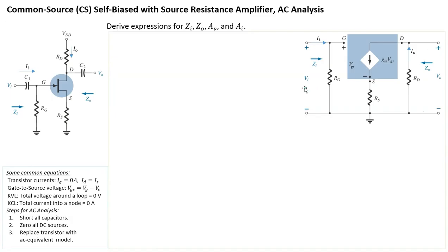That will be useful for us to work out the four components of interest. So let's start with IO. IO is a current that flows up that way and then goes left because there's nothing here. So it goes up, goes left, and comes down. Well, it is actually gm VGS. So IO is actually gm VGS. It comes down, goes across, and goes back up again.